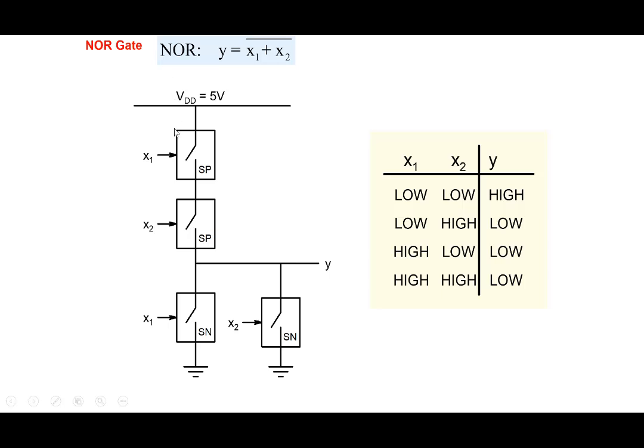So if I give you a NOR gate, how do you create an OR gate? Well, before that, how do you create a NOT gate? Given a 2-input NOR gate, if you take X1 and X2 and short them, so you have one input, you will see that Y is nothing but the inversion of X. So if you short X1 and X2, it becomes a NOT gate. And it's already a NOR gate. So if you take a NOR gate and connect its output to an inverter, or a NOT gate, the whole thing becomes an OR gate.